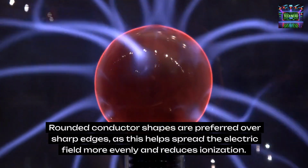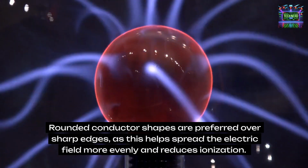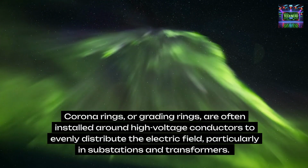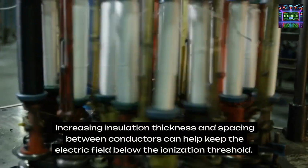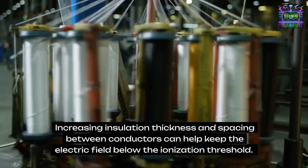To manage corona discharge, engineers use several design strategies. Rounded conductor shapes are preferred over sharp edges, as this helps spread the electric field more evenly and reduces ionization. Corona rings, or grating rings, are often installed around high-voltage conductors to evenly distribute the electric field, particularly in substations and transformers. Increasing insulation thickness and spacing between conductors can help keep the electric field below the ionization threshold.